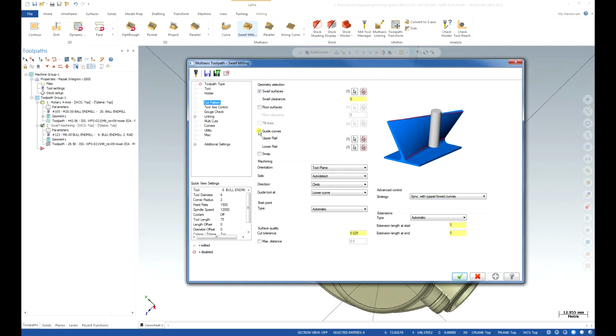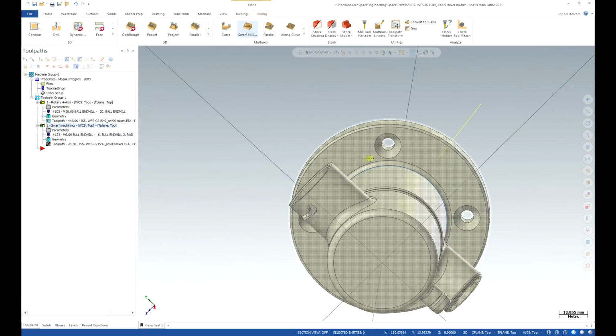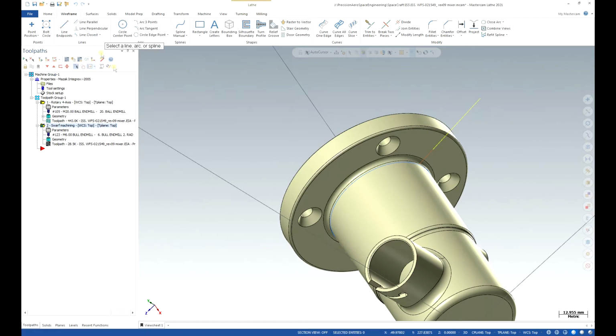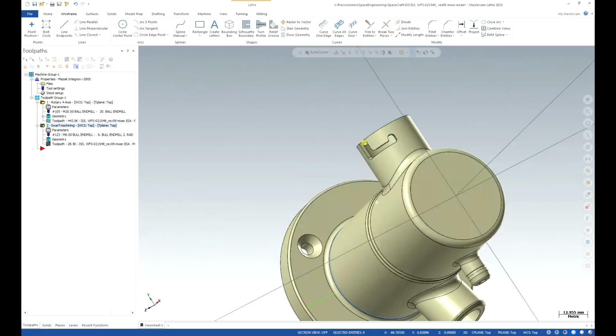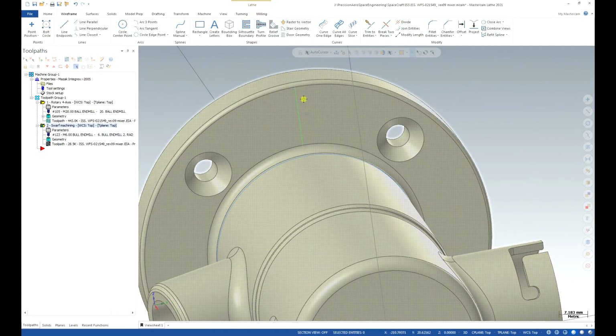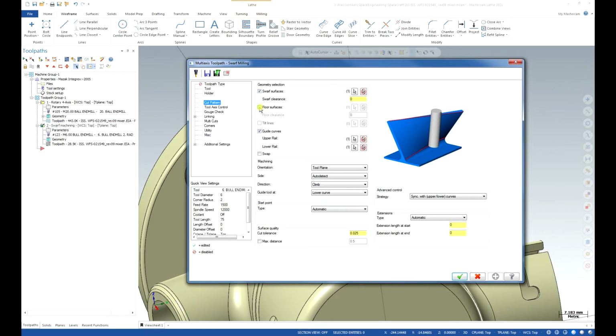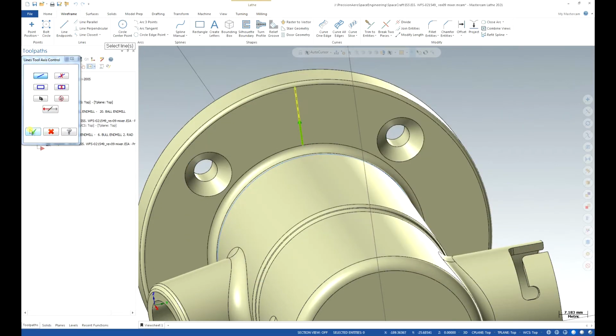The other way you can do it is by tilt lines. So let's create a tilt line for a sec. We're going to wireframe, line closest between that, and this is our tilt line. Okay, we will use this line as a tilt line. So we don't want the guide curves. Now it's turned off, so we need to select our tilt lines, and it's enough to have one. So let's select the one tilt line we have here.